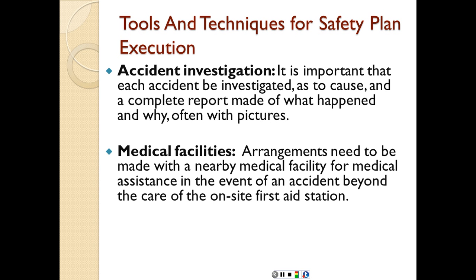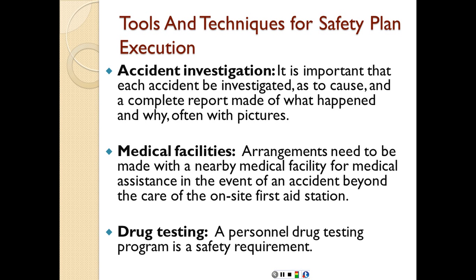Medical facilities. Arrangements need to be made with a nearby medical facility for medical assistance in the event of an accident beyond the care of the on-site first aid station. We definitely have to have a first aid kit available on site to treat minor injuries and things like that, but for major injuries, what would be the closest medical facility that can take care of that injury? Drug testing. A personnel drug testing program is a safety requirement, and it's a contractual requirement as well.